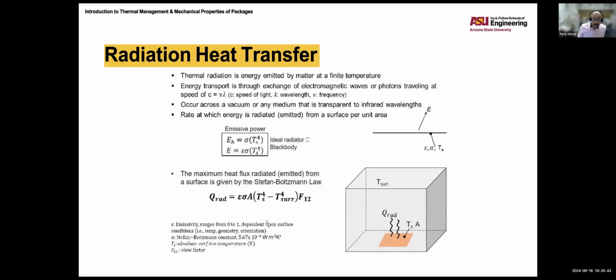Let's look at the first one: new interconnect metals need new dielectric. If we go back to the mid 90s, when copper metallization was just coming on the scene, there were a few holdovers like Texas Instruments who wanted to ride out aluminum as far as they could and focus on low-K dielectrics.